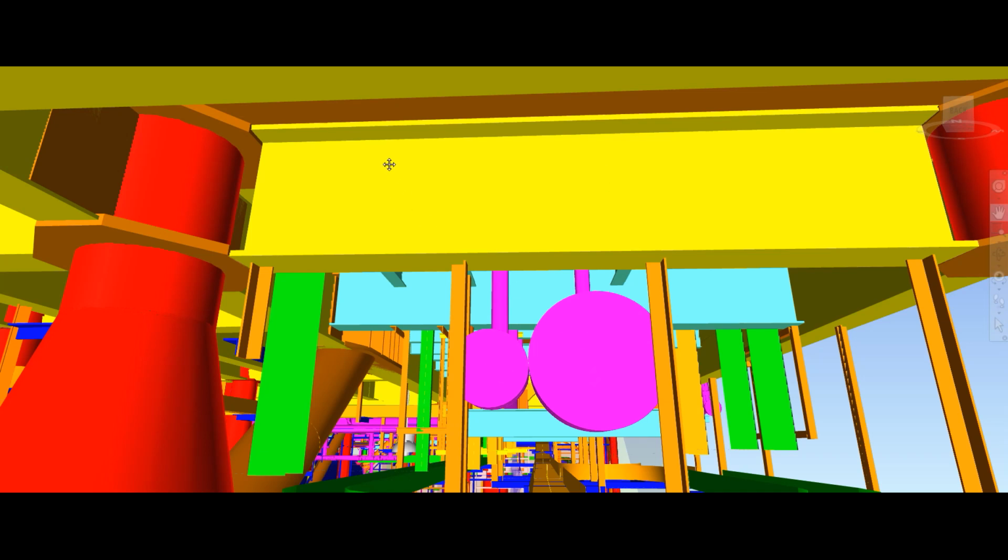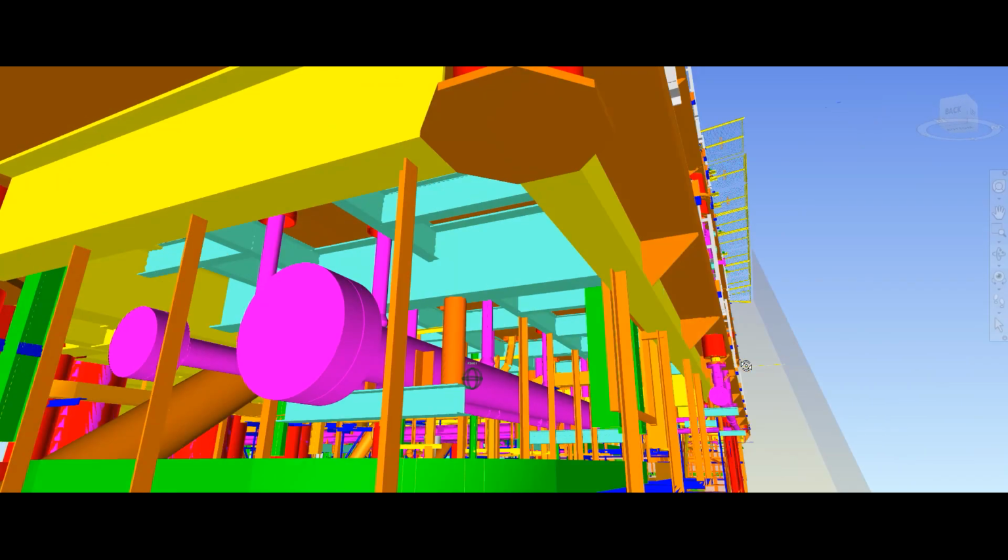So the line from the choke valve, there is a check valve after that, and then after the check valve the line splits into two. One is coming to this production header, the other one is going to the test header. Before going to the production header or test header, we have MOVs installed on each split line, globe type MOV valves, where the upstream side is 3000 rating and downstream is 1500 rating. For the production header we have the MOV valve, and for the test header we have an MOV globe type, because we have to test that line. The test header and the production header are again 1500 rating, but it all depends on the company and project to project.